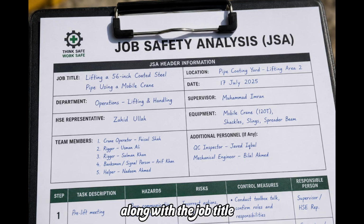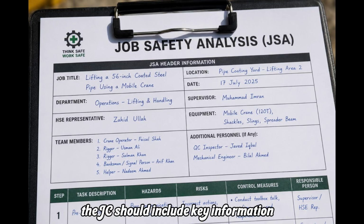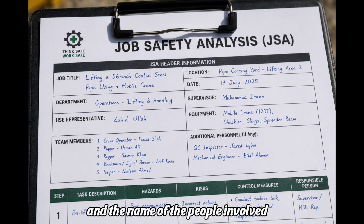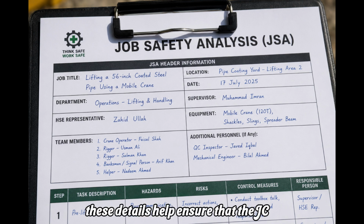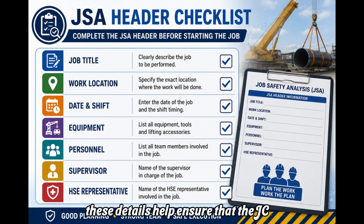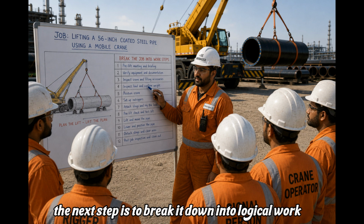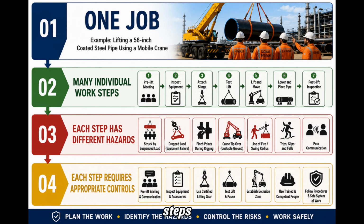Along with the job title, the JSA should include key information such as work location, date, shift, equipment to be used, and the names of the people involved. These details help ensure that the JSA applies to the actual work being performed and not to a different task or location. Once the job has been clearly defined, the next step is to break it down into logical work steps.